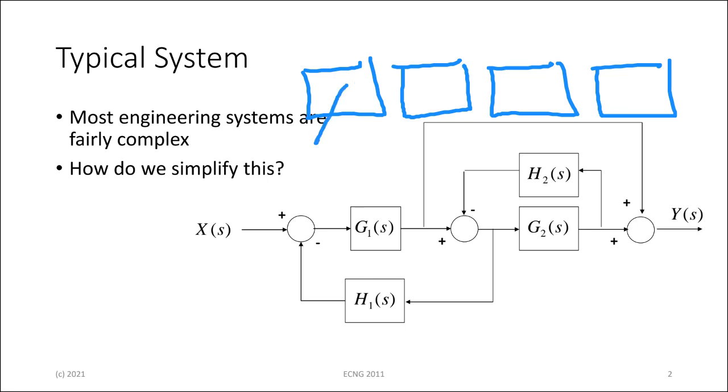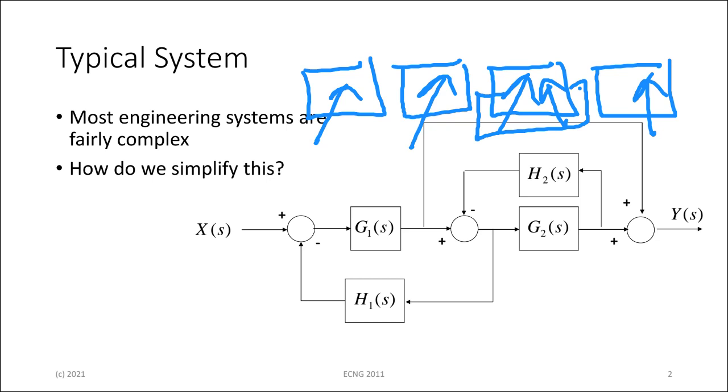In the rectifier section, you will deal with just the diodes and the transformer and maybe any fuses and the like. In the filter section, you have that big filter capacitor to deal with. The regulator section is all of the electronics that we spoke about, and then the protection section will be the overcurrent and short circuit protection that we dealt with, and we looked at two of them. Plus you can also put additional fuses inside. And in this section will also be, if you have a variable supply, how you vary it. And there's some feedback in this section too. The regulator works with feedback.